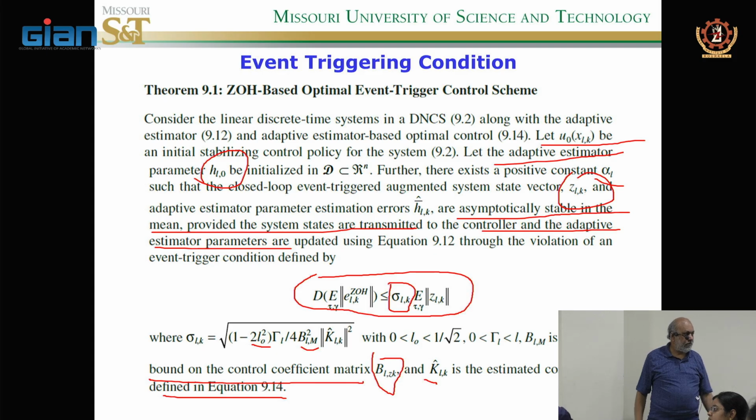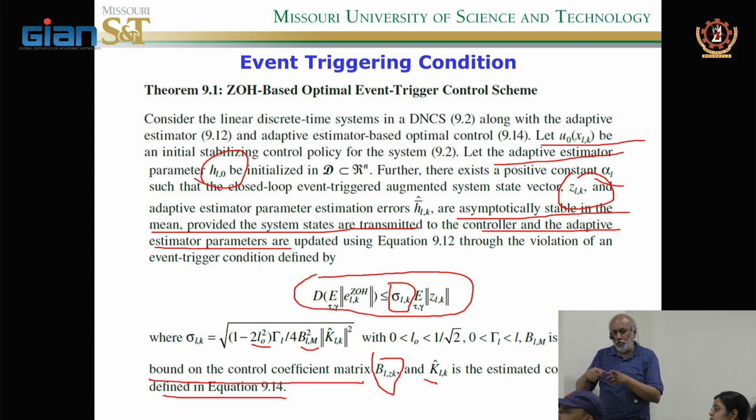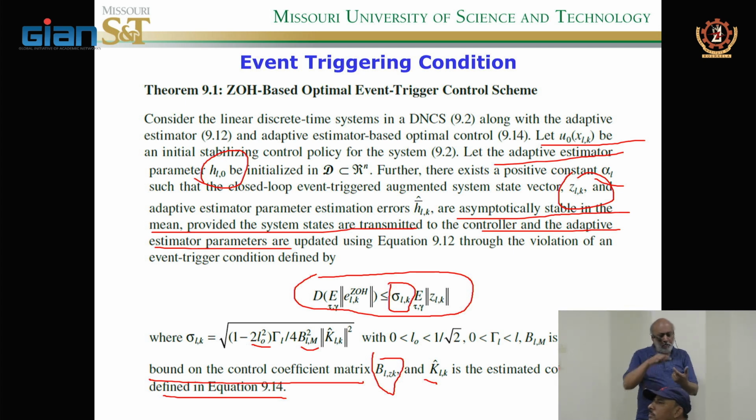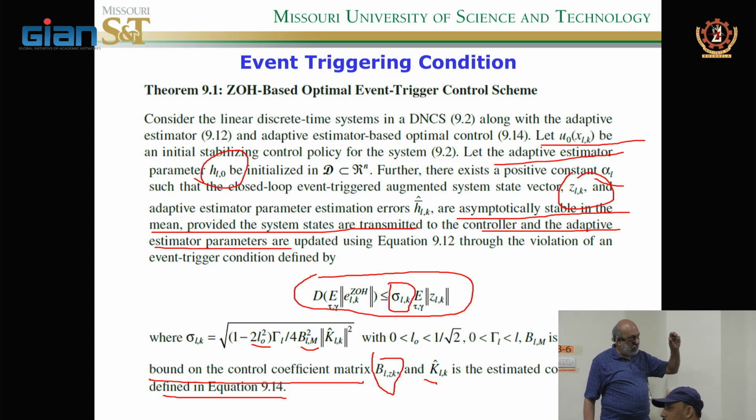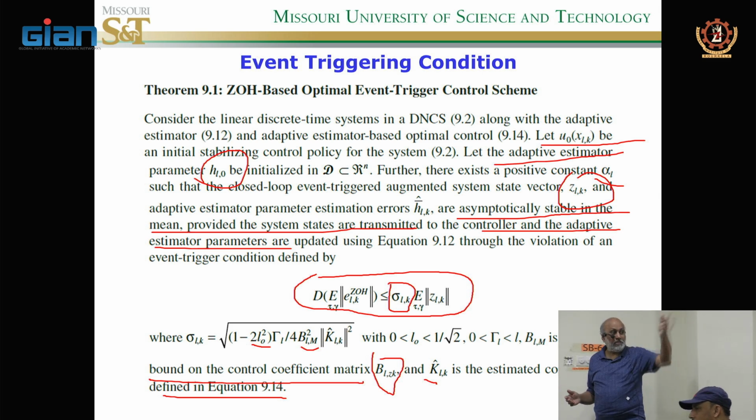Whereas in event triggering, you don't fix it. That fix is there, but then you will be transmitting as a function of those fixed intervals. So you don't transmit every time, maybe once in 5, based on that design. That's called event. Event means the threshold. Whenever the error hits the threshold, then immediately you transmit. We call that an event. But what happens if you don't transmit? The system will become unstable. That's what he was asking earlier.